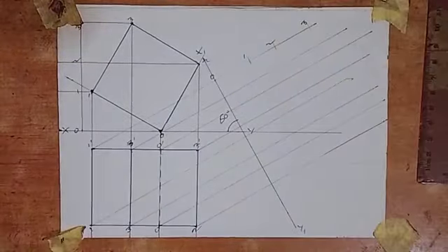All right, so then the next thing that we have to do is to transfer these points to this side. With the set square, we transfer the points. You have to use the 60-degree side so that the lines can be parallel to the x1, y1 line. So draw the line like this and come to this point. You also draw from here to here, and then come to this point 3. You also draw like this. Okay, so we have this now.